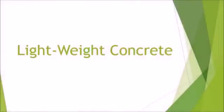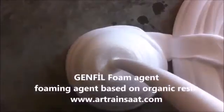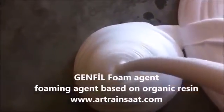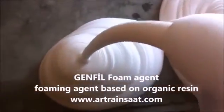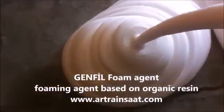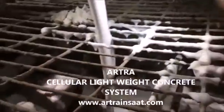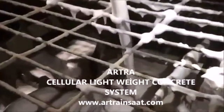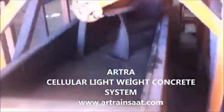Lightweight concrete, also called foam concrete, is a versatile material which consists primarily of a cement-based mortar mix with at least 20% of volume air. This volume air comes from a foaming agent that is mixed with the cement binder to form the concrete mix. The material is now being used in an ever-increasing number of applications, ranging from one-step house casting to low-density void fills. Generally, it has excellent thermal and sound insulating properties and a good fire rating.